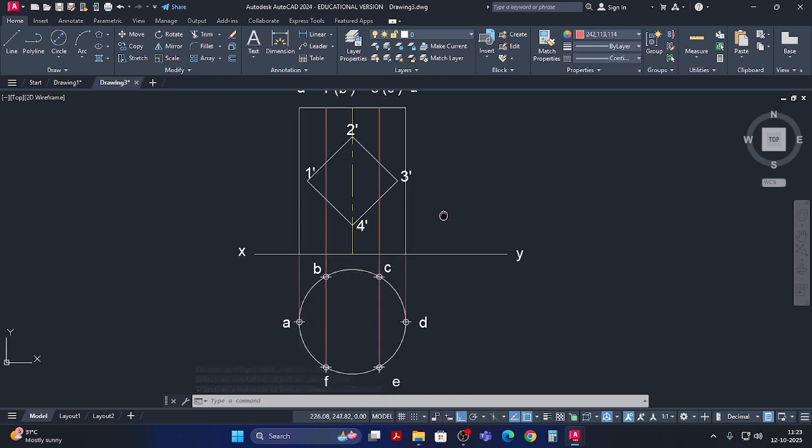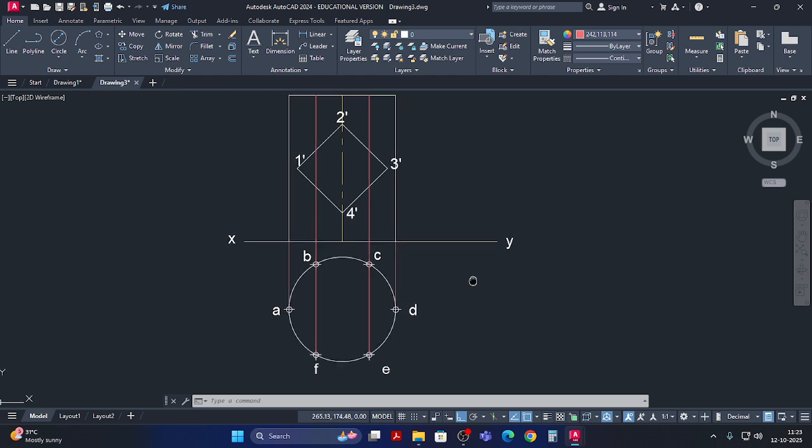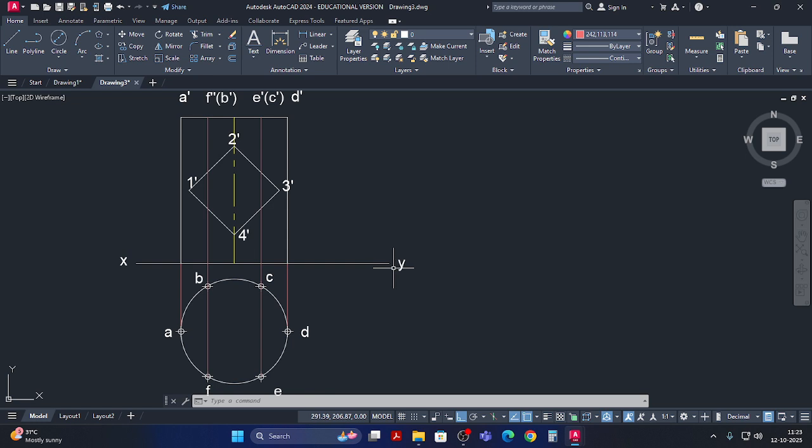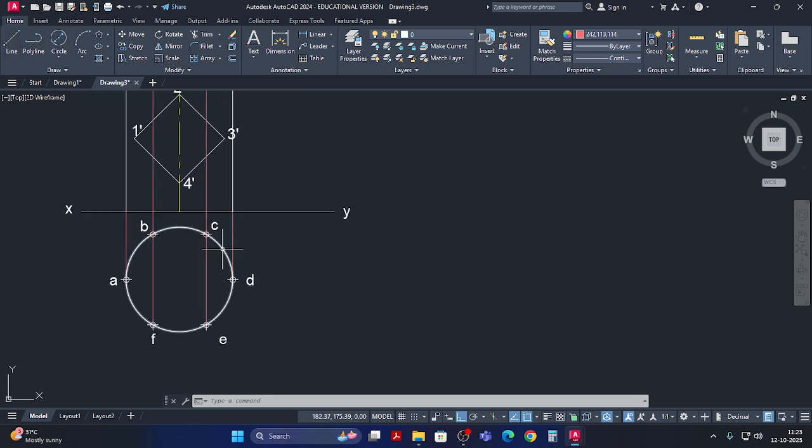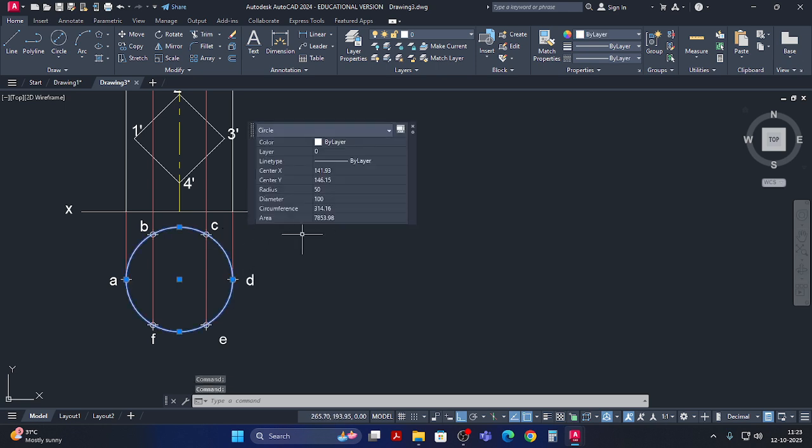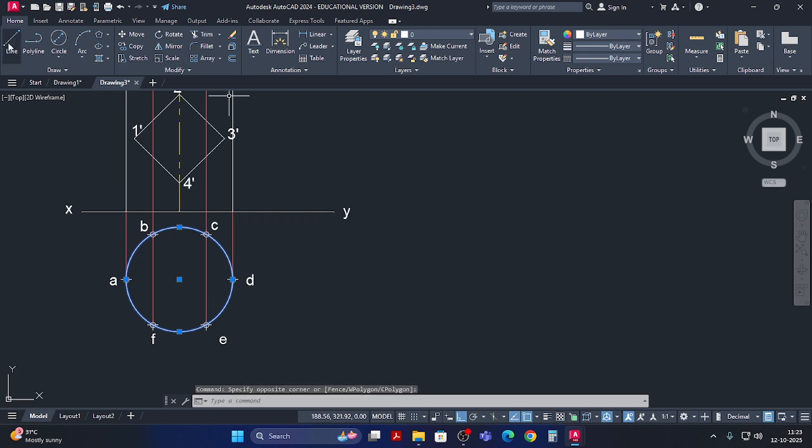Now we need to open the lateral surface of the cylinder here nearby. So we'll double click the circle, top view. Two length will appear in the top view. Two distance 314.16. That is the circumferential perimeter. So accordingly we will draw a line straight to this, because then only we are going to project this. Straight to this. You select the bottom.